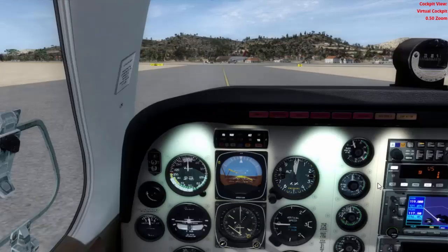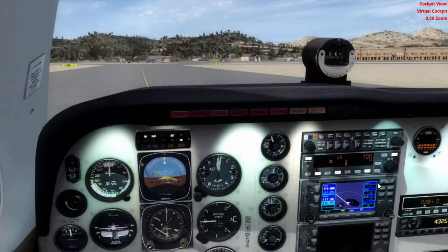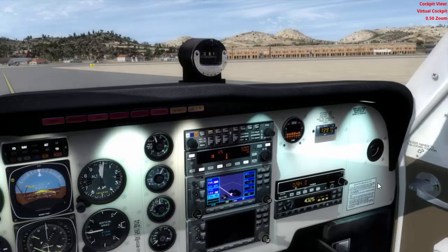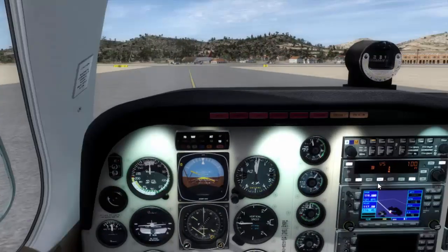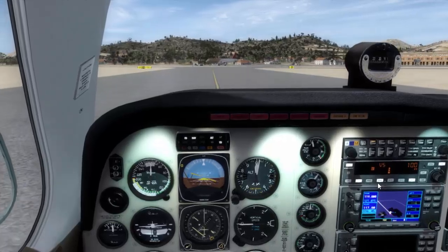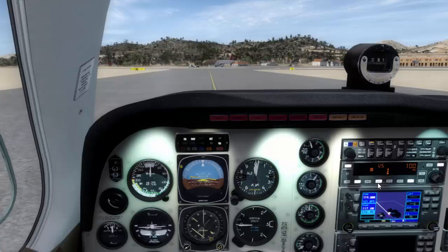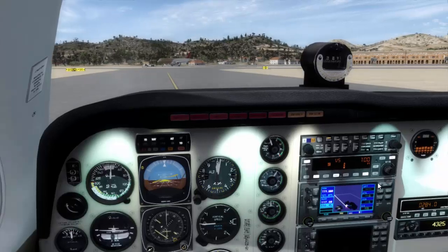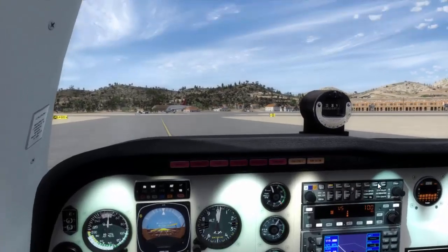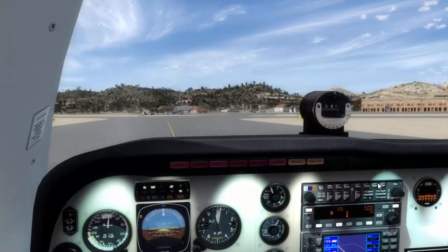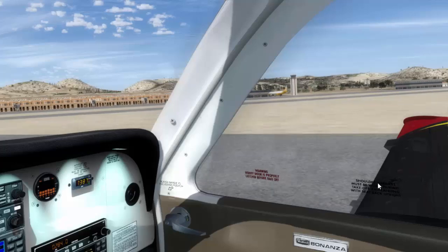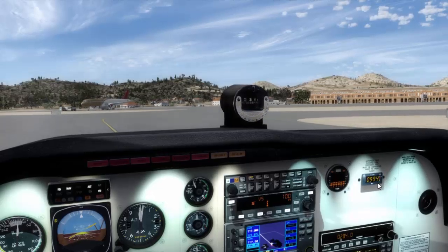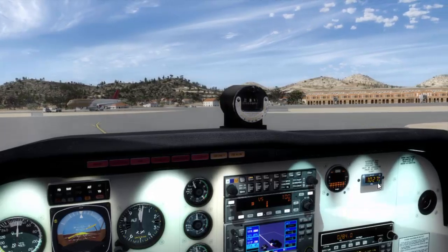Okay, so basically we will move a bit forward the black lever and we will get some RPM. You can see that in the digital counter to the left side, by the way, 1000, 1400, 1500 more or less RPM. Okay, and our aircraft will start to move little by little, and the yellow line is the line we must follow, okay, to have our aircraft properly aligned with the taxiway. Okay, and here we don't have a magic finger like in the Nintendo or PlayStation or Xbox.